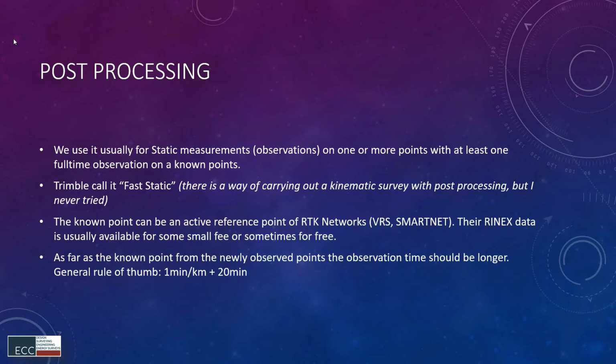Sometimes, especially every hour, maybe once, it's worth going back to see if the battery is still alive, still flashing or something. And then at the end of the day, you can go back and stop the survey, and before you disconnect, you can export into the logger and then put it onto your USB stick, and all your data will be on the USB stick at the end of the day.